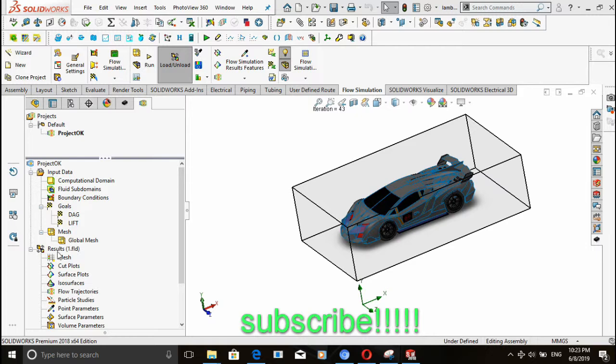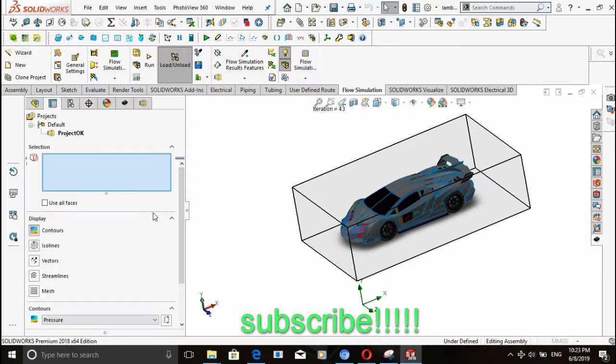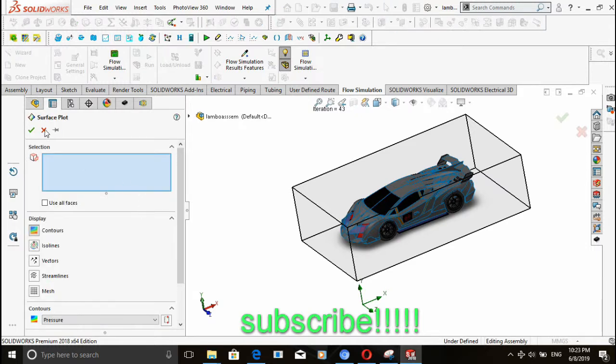If you discover that your results have not been loaded, you just right click, or you come here and choose load. So what I'm going to do is this. We are going to go to plot surface, right click, and choose add. But permit me, before we do this, I'm going to close this.